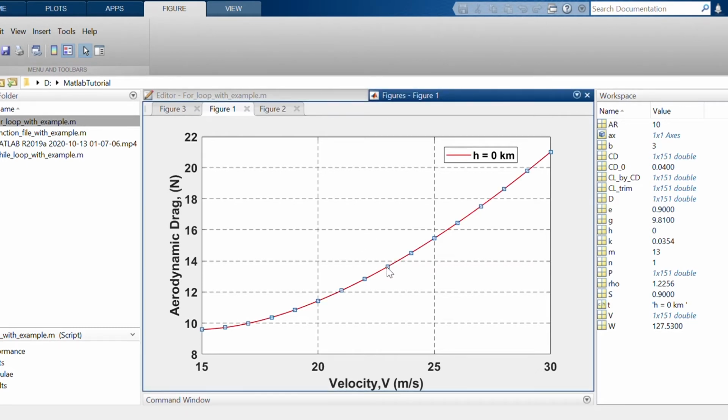If you don't like this solid line, you can go to the line style and make it dash. You can see so many options are available like line style, dash, dot, dash dot. Just check how dash dot looks. Fine. You can also increase the line width. Currently it is 1, right? If you increase it to 2, it will be a little thick.